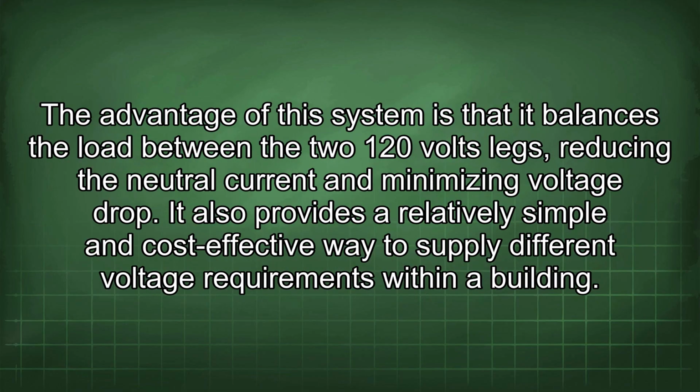The advantage of this system is that it balances the load between the two 120 volt legs, reducing the neutral current and minimizing voltage drop. It also provides a relatively simple and cost-effective way to supply different voltage requirements within a building.